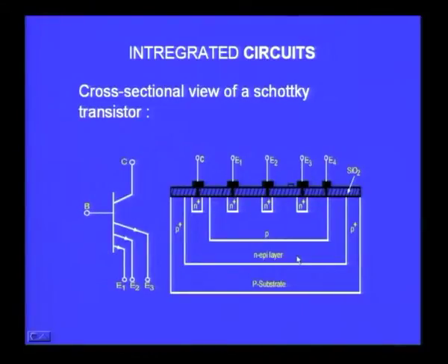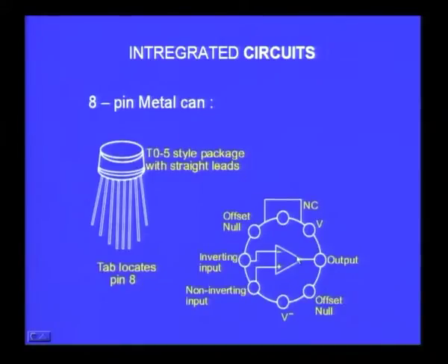This is one great advantage, especially when you go to logic circuits and things like that, where you require multiple inputs. ICs look very similar to transistors. For example, I have shown here different types of encapsulation, how the IC is mounted. For application, you have to take the small silicon chip, mount it onto a package, and then take the leads to the pins of the package, so that externally you can put them in a given circuit and form the different application circuit that you want.